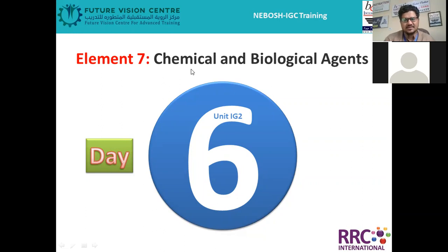Like H2S, hydrogen sulfide: a colorless gas, heavier than air, extremely flammable, extremely toxic, poisonous, having a certain level of LEL and UEL, also an extreme level of ignition temperature. Most importantly, it can kill in minutes and seconds if the ppm level is ignored or the gas testing is not done, especially in our confined spaces.